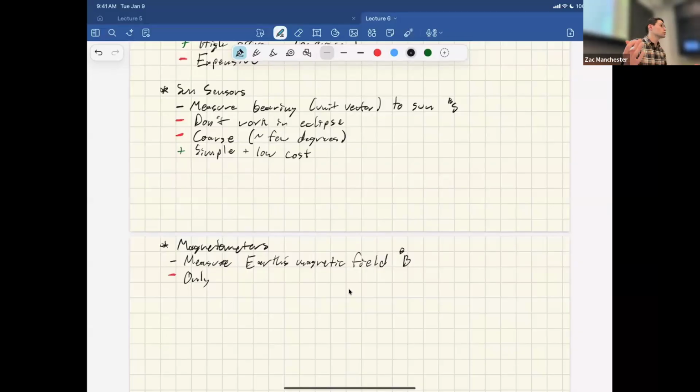It turns out, to do this, it's similar to the star tracker thing. You need a map of the magnetic field. And one of the subtleties here is you actually have to know where you are too, right? For this to work, you have to know what the B vector in the inertial frame is for this to be of any use. To know that, you have to know both your position and have a good map of the magnetic field of the Earth to look up what it should be, and then have both the inertial frame and the measured body frame version, right? These are subtle points. If you don't have orbit knowledge, you can't do this because you don't know what the inertial frame B should be in that location.